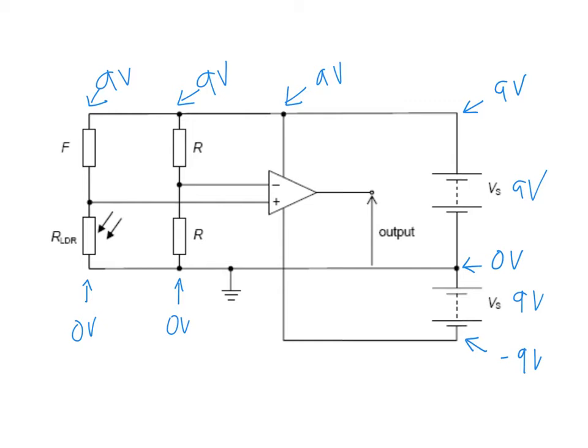But we must always take the PD from the 0 side, 4.5 volts, to get the potential at this point. So this point also has a potential of 4.5 volts. So this becomes your V minus, because can you see it's connected to the inverting input here? So your V minus is 4.5. But will any current flow in? No, current just flows down like that. Understand that? Why can it not flow in? Remember the assumption is infinite input impedance. Okay, so no current enters.